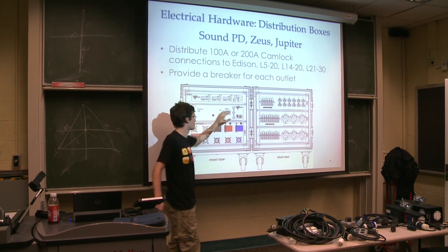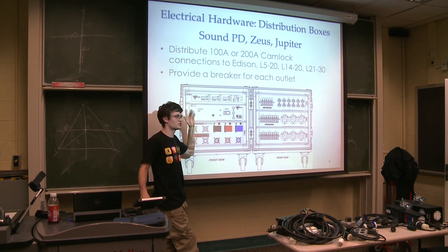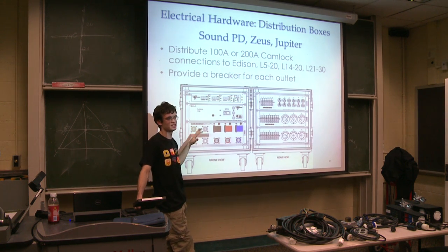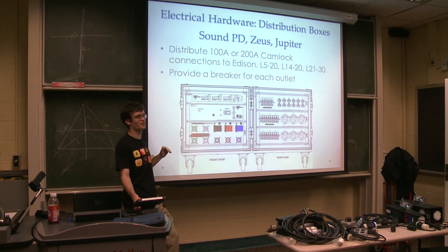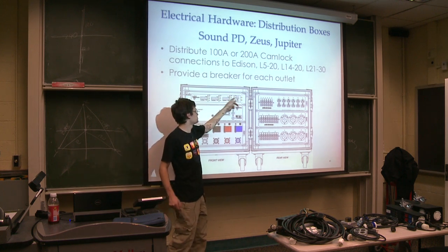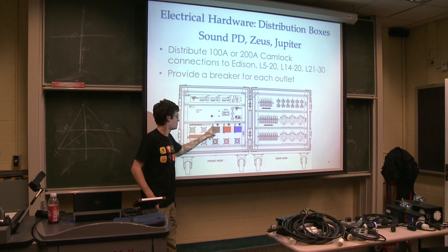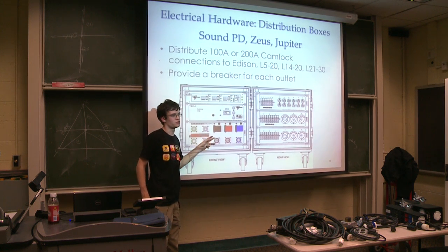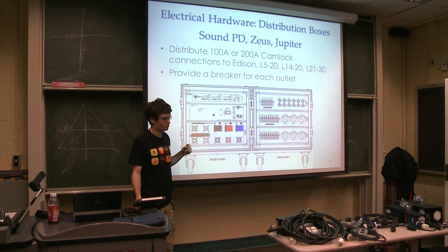It's just going in through the main breaker into the rest of the box. The current meters also don't really show for under about 7 amps or so. So if it's showing 0, but there's stuff on it, there actually is current flowing. You're just not seeing it. And you can hit the bottom button and switch between 120 volt to neutral, hot to neutral, hot to hot, current, and frequency.